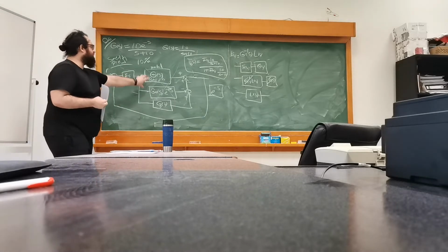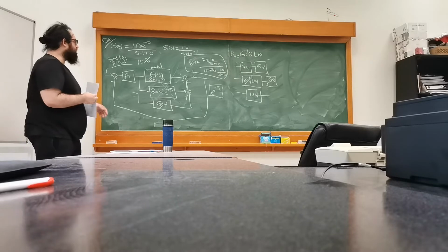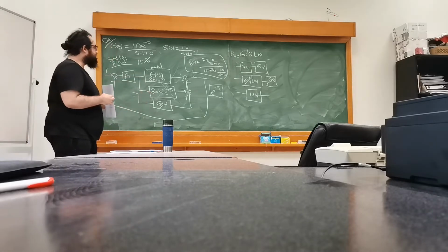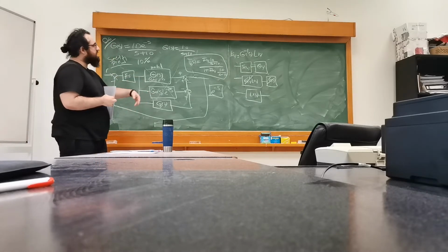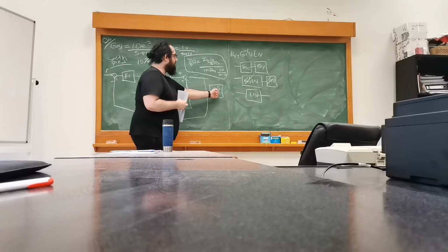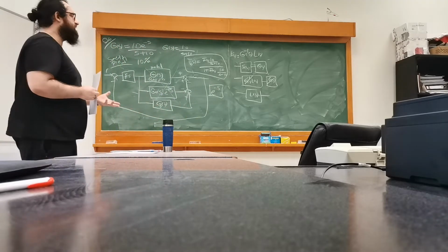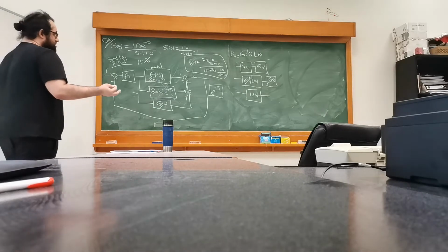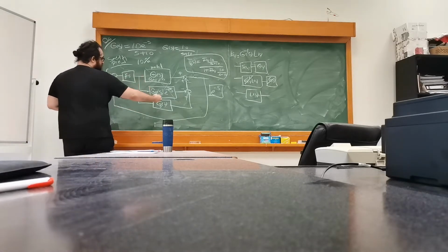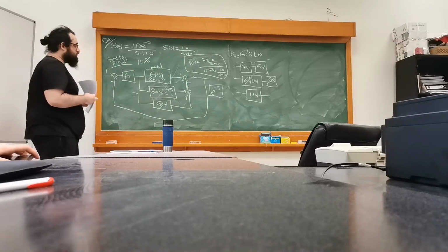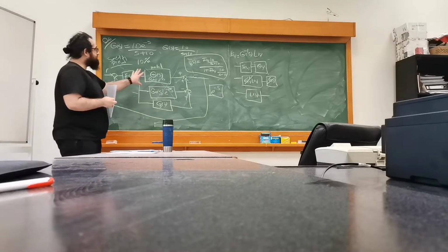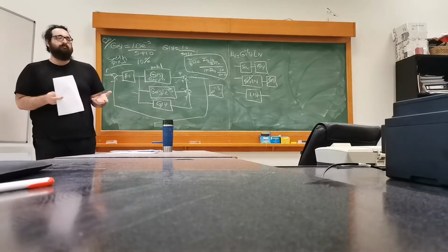And you can see that by using the relations here. If you look for the closed loop transfer function, you'll see that in the closed loop you still will end up with a forward term that has the delay. Of course, you cannot get rid of the system delay, because it doesn't really matter what your controller is or what your control structure is. The system responds with a certain delay.